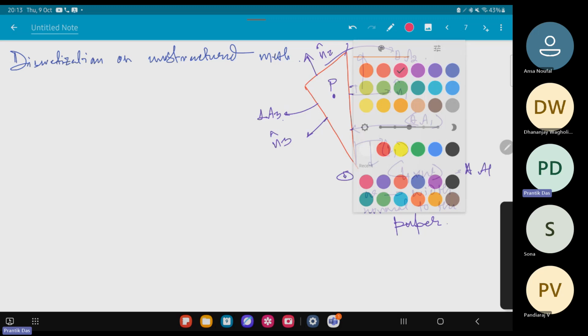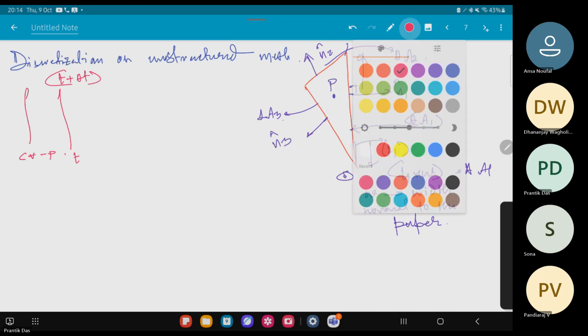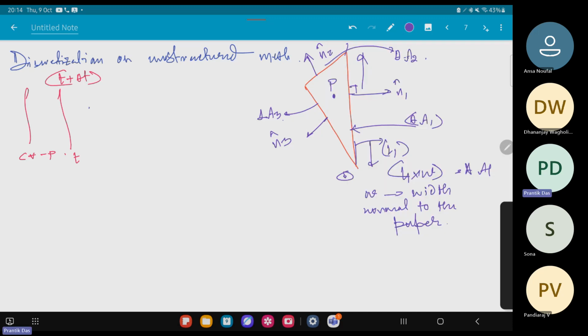So going to the general transport equation. It will be the integral over the control volume P and from t to t plus delta t of ddt of rho phi dv equals, so you have to integrate both with respect to the control volume and the time itself.